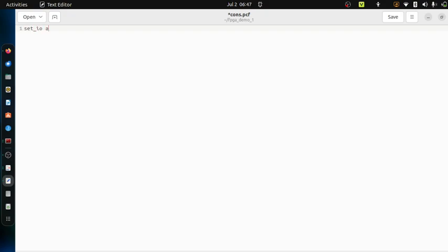First input is A, and we'll assign it to pin number 37, and second one is set_io B, which we'll assign to 36, and last one is the output: set_io C to 35, and just save it.